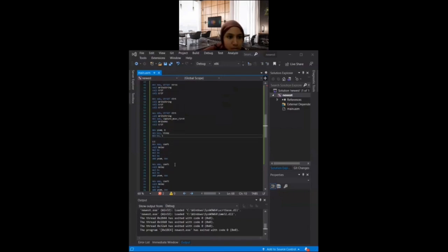And then for the loop part, this is for coefficient 1. For coefficient 1, we call the delay with coefficient 1 milliseconds, and then multiply it 3 times, because we compute x to the power of 3, and coefficient 2 times x to the power of 2, coefficient 3 times x to the power of 1, and then coefficient 4, we just add the result into the y sum, and then we end the loop. So if the loop counter equals 0, it will end the loop. And then we want to display string 7.